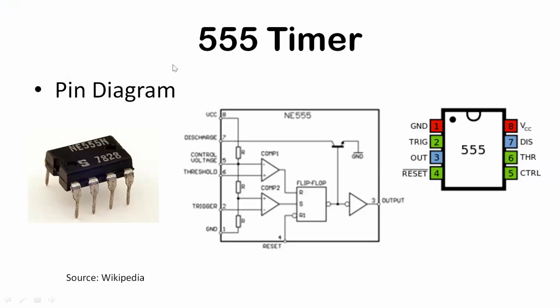It is commonly available as NE555, and there are also some other manufacturers. You can see the pin diagram. Pin number 1 is the ground. Pin number 2 is called the trigger pin, where you can apply some external input. We are taking output from pin number 3. Pin number 4 is used to enable or disable the IC, that is reset.